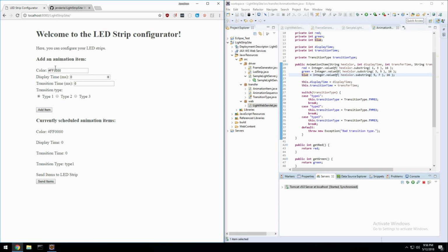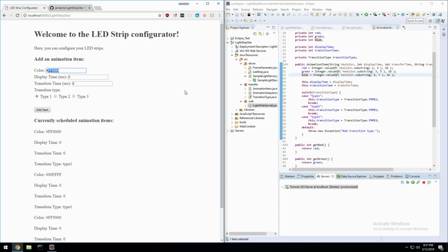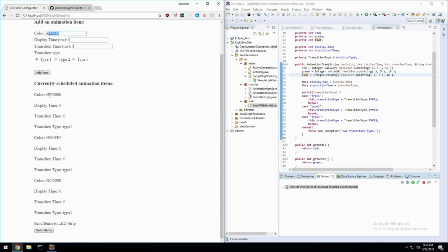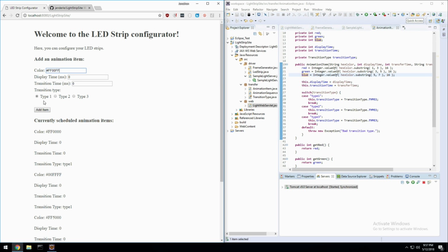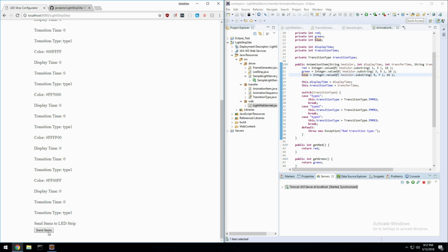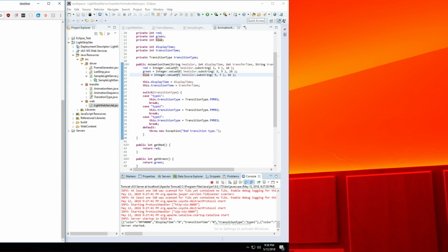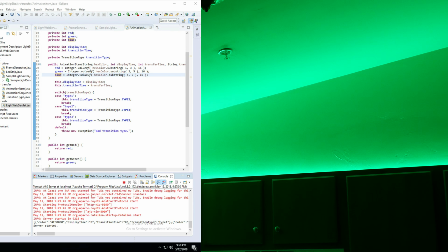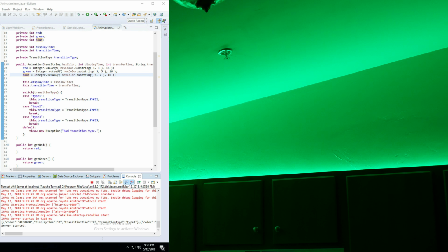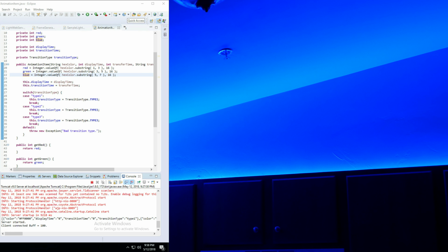When the Tomcat server is passed an animation set from a web browser client, it'll pass this information to the master thread. The master thread will then index through the requested steps in the animation sequence, generating the frames and pushing these frames into the incoming buffer of the connected LED clients in lockstep with one another. At this point, the slave threads, which are managing the individual TCP streams, will transmit the new frame to each of their clients, and then the next frame will be generated and transmitted once each of those slave threads sets their transmission complete flag.